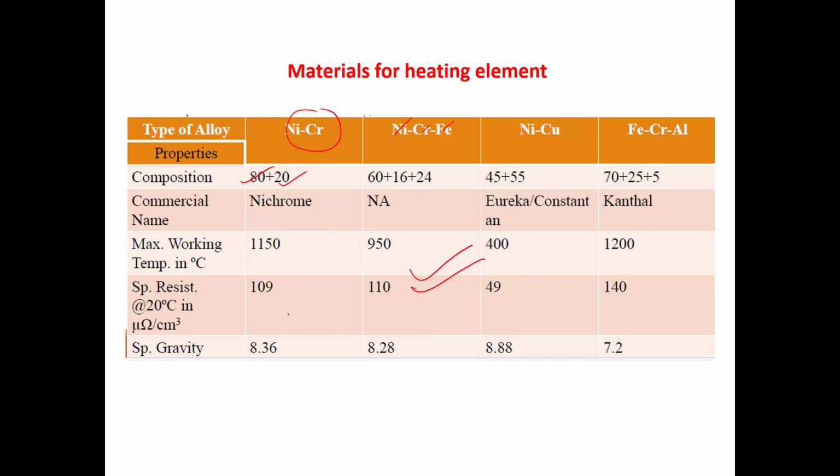But coming to this one, it has some oxidation effect there. That's why I'd prefer nickel, chromium, iron. Cost-wise also, it's cheaper. Yeah, don't forget this. The type of heating element here is nickel, chromium, iron.